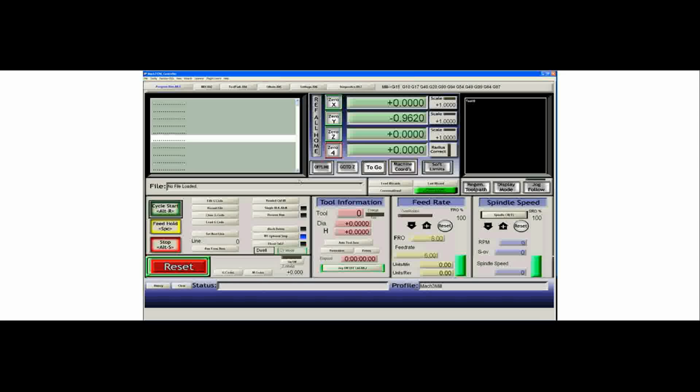That's it for the most common problems in getting Mach 3 to actually put out. A good way to check to see if your printer port is working is to use that auto pin input setup, because it will at least tell you if your printer port is working. If that routine works for you, your printer port is valid and your motor signals are likely going out, but your breakout board may be missensing the charge pump input, so you want to read the documentation on your breakout board to make sure that the charge pump is not your